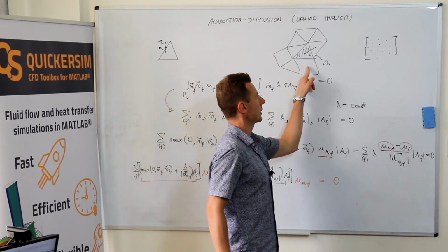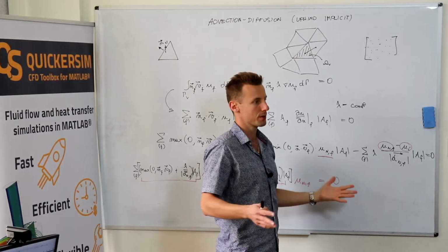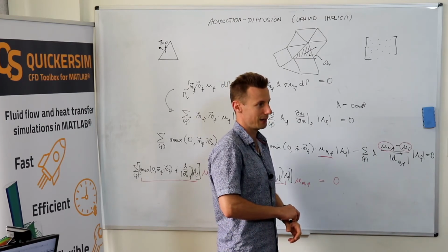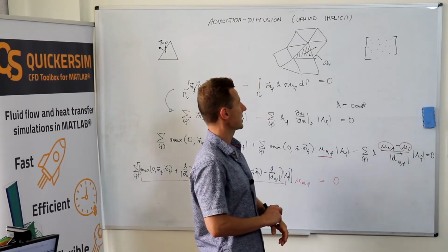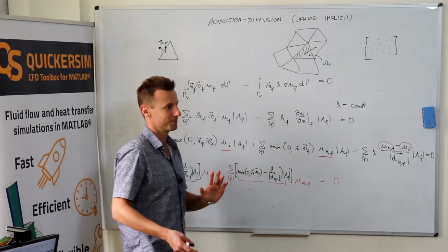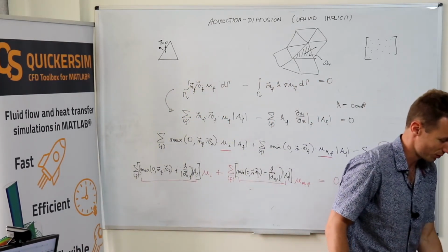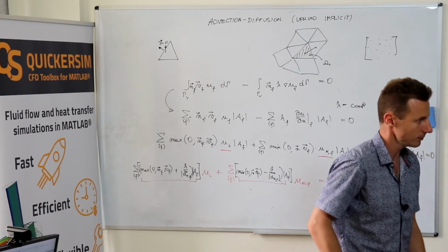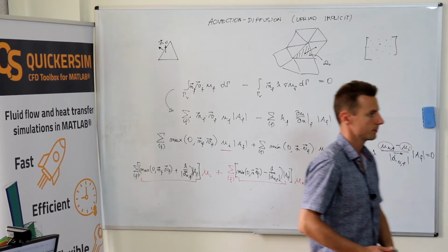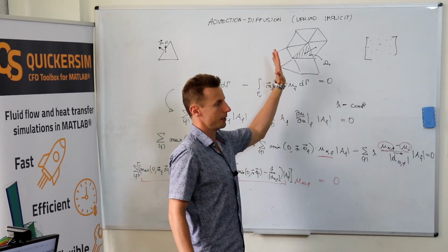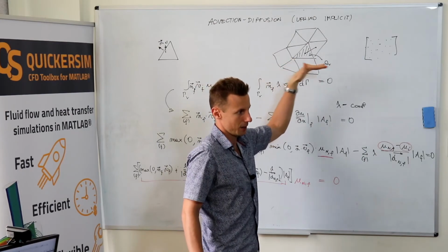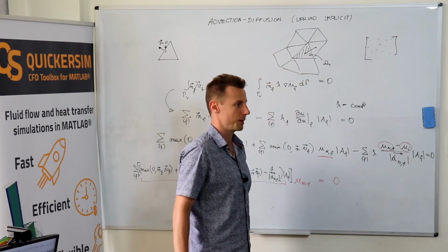Generally, quads are better when it comes to the number of unknowns that you would have in the system compared to the number of cells. So it's nice to have quads if you can have them, but fully automatic meshing algorithms only exist for triangles, for arbitrary geometries. So it depends. Choose one. Also, if we've got flow in one direction, the structured mesh introduces less numerical diffusion. Yes, that's right. If you've got flow whose direction is aligned with the grid lines, then you have little numerical diffusion.